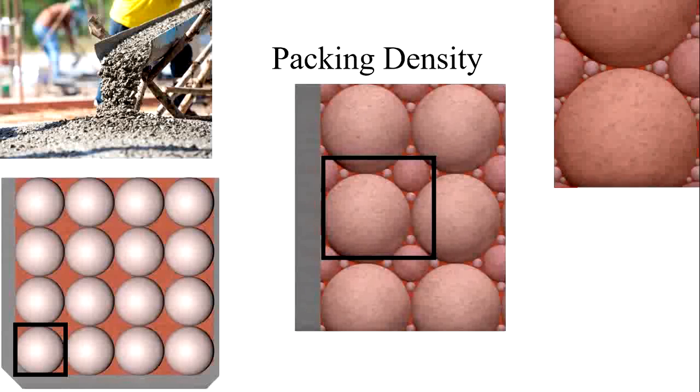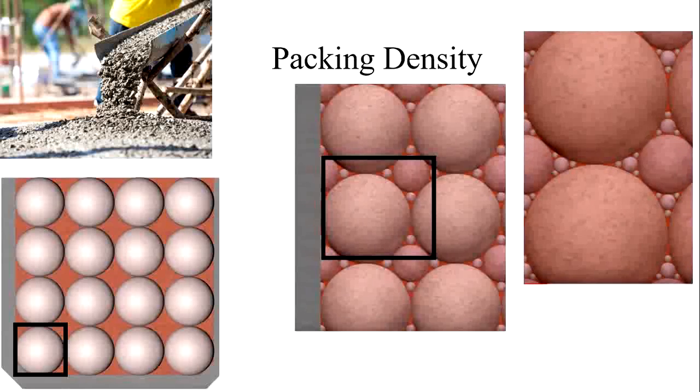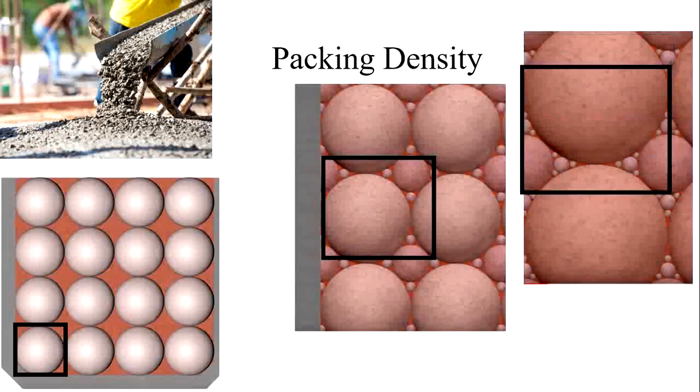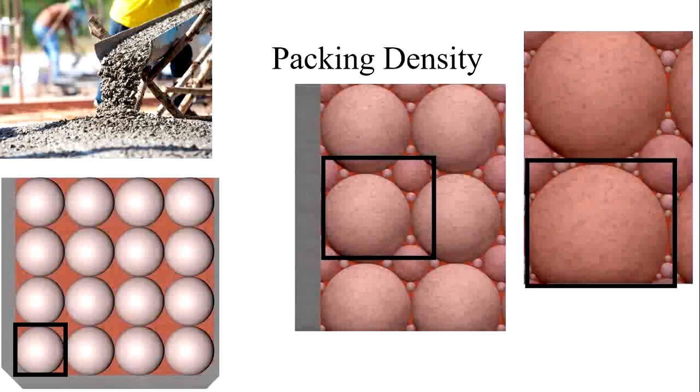And finally, when the coarse aggregate, the fine aggregate as well as the cementitious materials are present in concrete, now if you calculate the volume of a single portion, the air voids are much reduced. Now if you calculate the percentage of air voids, from the above two figures, we'll be able to see there is a much lesser content of air voids present.